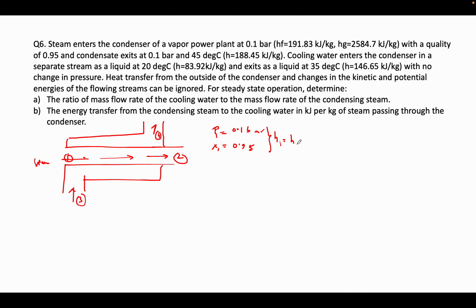H1 will be hf at 0.1 bar plus x1 times hg at 0.1 bar minus hf at 0.1 bar.